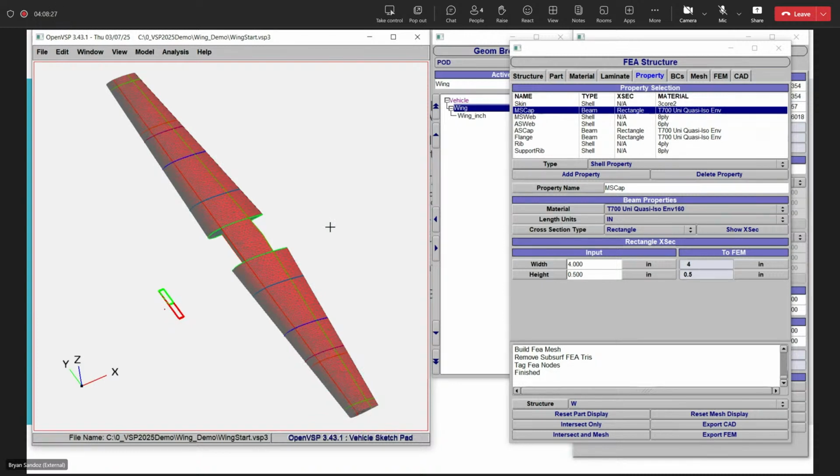And that's the point where things tend to slow down, I think, with traditional structural analysis: you do all this work in CAD to make this wing bigger, then you hand it off to an analyst. The analyst recreates a whole FEM from scratch or modifies a FEM to make it work, and then runs through that loop as well. So this is really where having the structures tool coupled with an aero tool, coupled with a design tool all in one is really helpful.